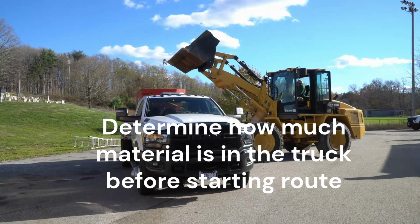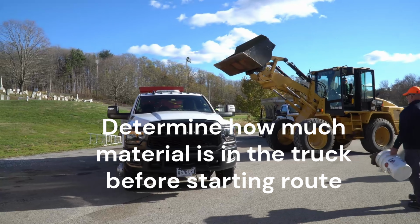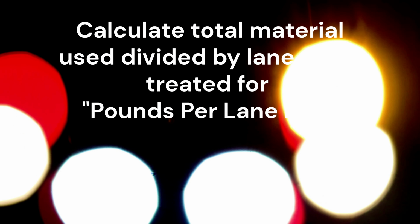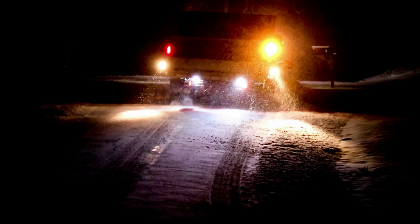To complete this test, determine how much material is in the truck before the route segment, run the route under normal operating conditions, determine how much material remains after the route, calculate the total material used, and divide by lane miles treated to determine actual pounds per lane mile.